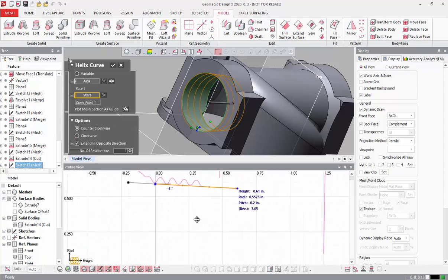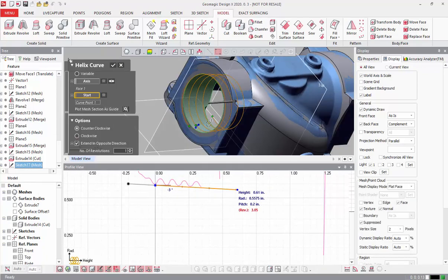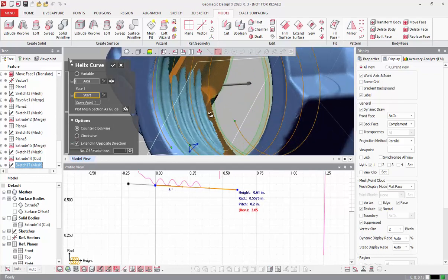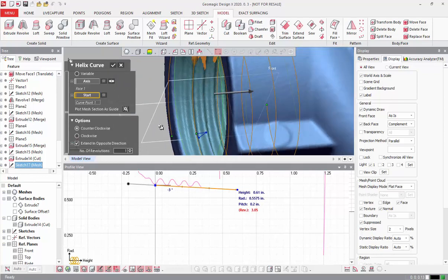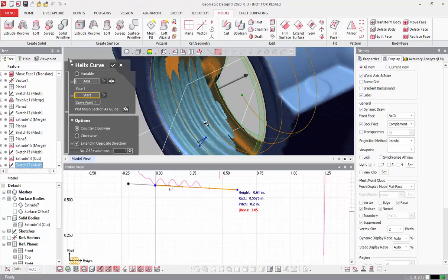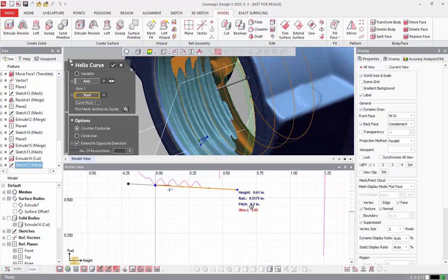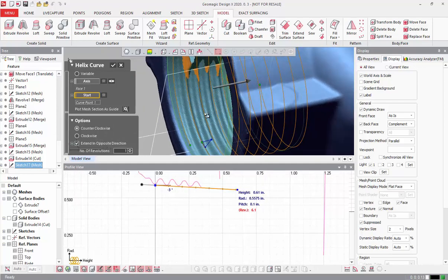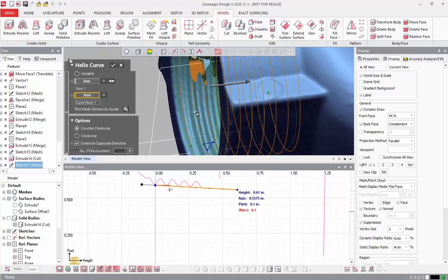So right now the pitch is set at 0.2 inches, and that's going to be the spacing, I guess, here. So if I change this, the other thing I like to do is just have my threads on screen, this is easier for me, just making sure I'm chasing one thread all the way around. And it looks like I need about double what I've got here. So, or yeah, half as much spacing, I guess, is really what I want. So that gets me a little bit closer.